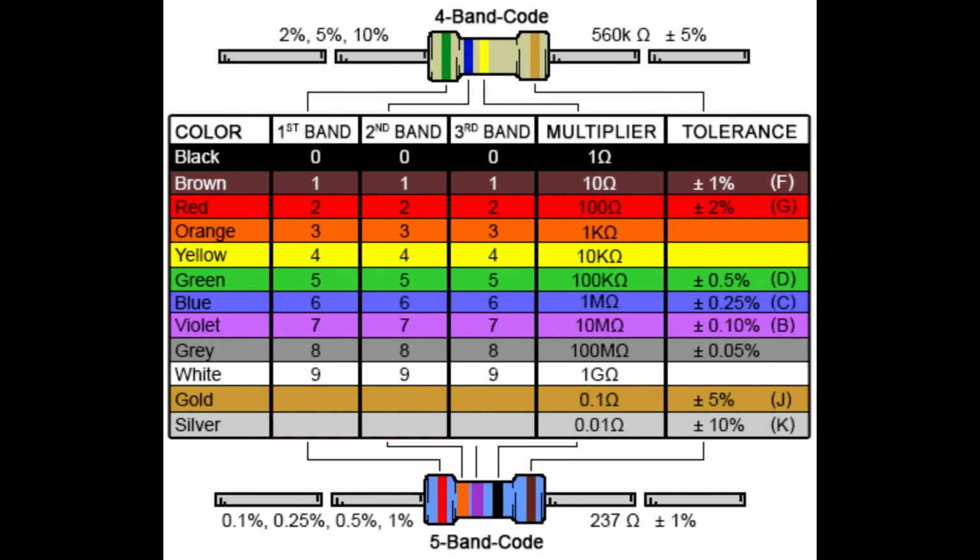All the resistors have bands of different colors on them. The beginning band is opposite of either the gold or silver band, and that's your first digit. And that first digit will be the value of the color that it is. And you'll have a second band, a third band, and a multiplier. This is how we'll determine what this resistor represents. Just become familiar with this. We will learn more about this as we go along, and this will come to you easily after a while.